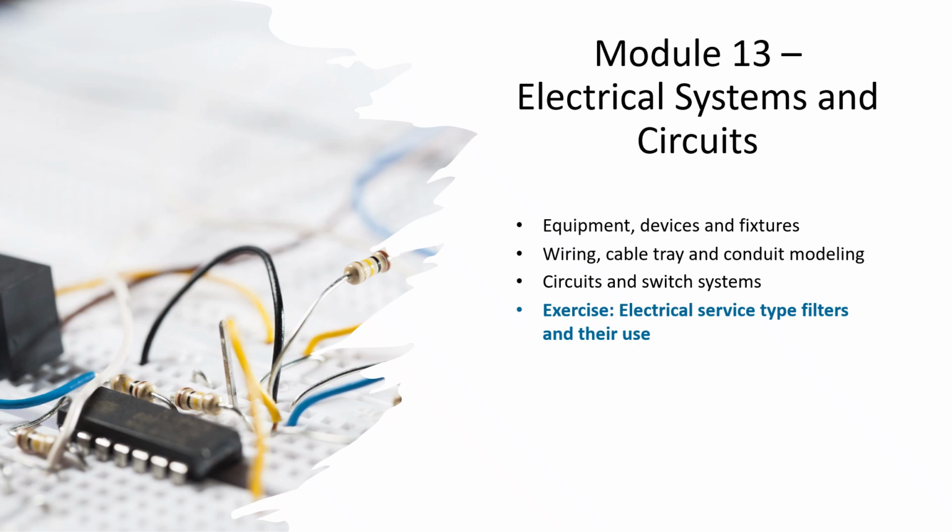Next, we look at wiring, cable tray, and conduit modeling. Revit allows us to route electrical paths with precision, ensuring coordination with architectural and structural elements. We then dive into circuits and switch systems. You'll learn how to assign devices to circuits, define panel connections, and simulate switching behavior, all within a coordinated model.